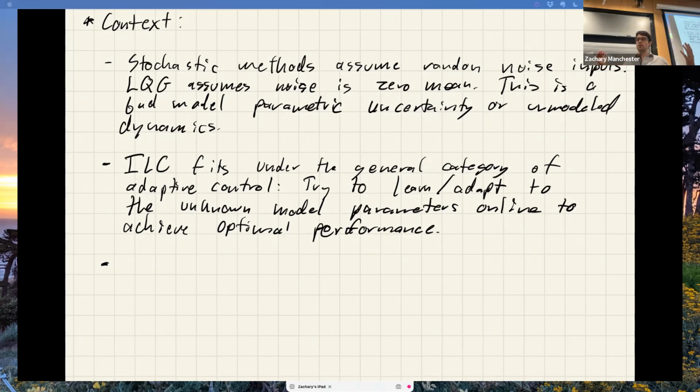You say, here's my model, I think there's 10% uncertainty in these parameters. Then you try to design a single control policy ahead of time, offline, that does not adapt. This one policy is going to guarantee stability of any particular system within that set of bounds, right?